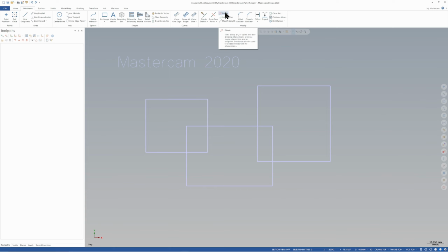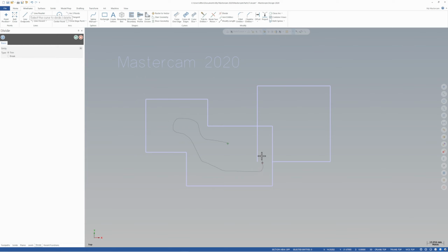is that when I choose divide, if you hold the mouse button down, you can drag your mouse around and anything it touches will get deleted. Just going nice and slow here, make it hopefully clear. When you let go, the little squiggle disappears and that's the end of the trimming function. If you do it again, anything it touches will just go away. So be a little bit cautious about how long you keep your mouse button pressed down for.